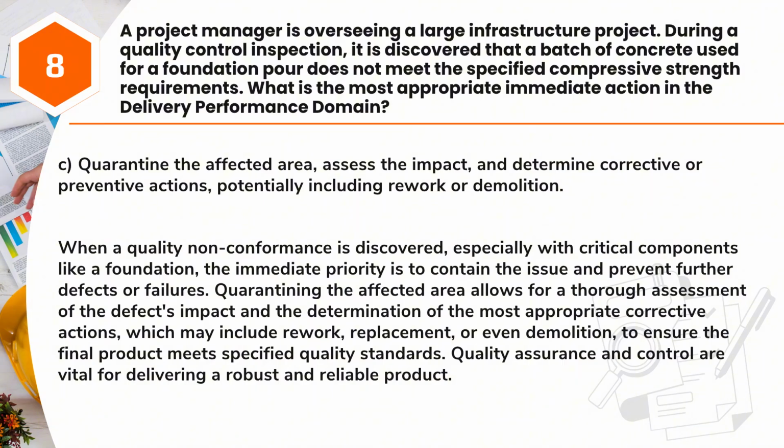Answer: C. Quarantine the affected area, assess the impact, and determine corrective or preventive actions, potentially including rework or demolition. When a quality nonconformance is discovered, especially with critical components like a foundation, the immediate priority is to contain the issue and prevent further defects or failures.